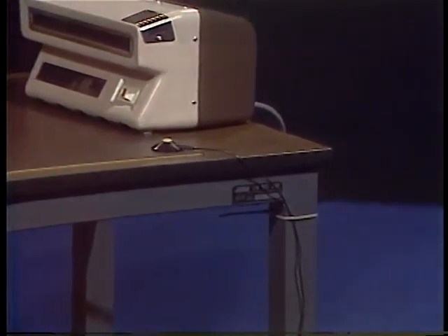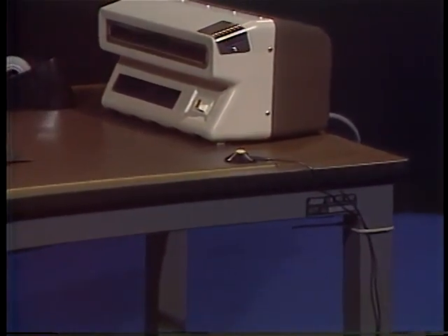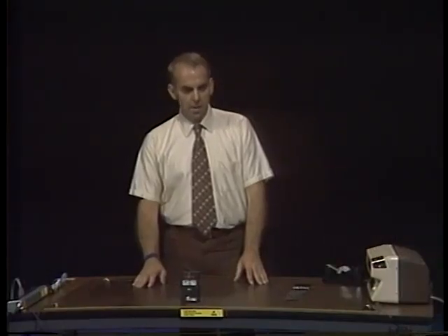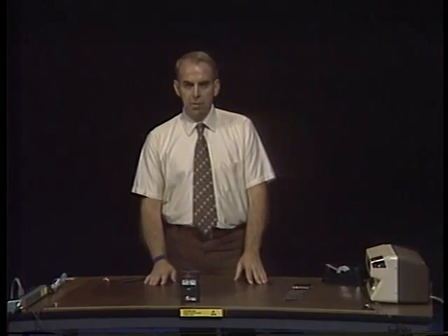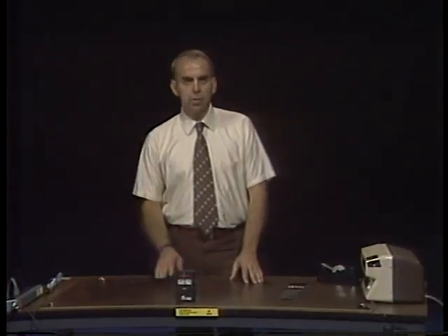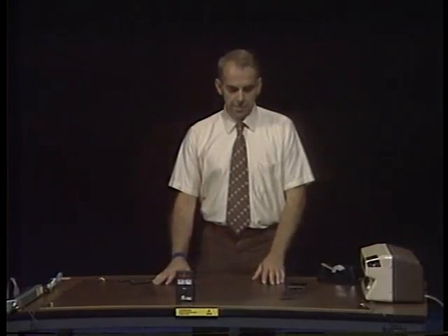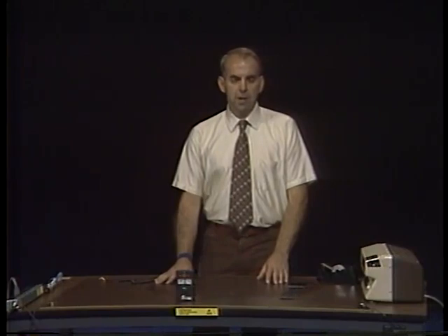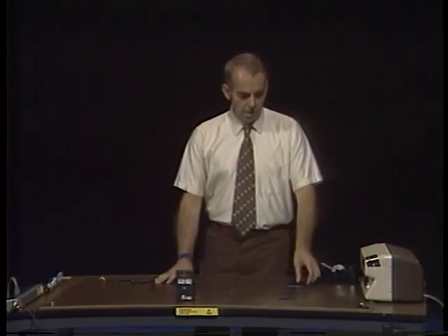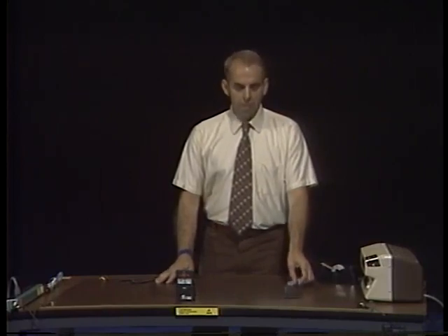Now the floor, the table, and I are all at the same potential. In the event that a table mat is not used, the floor mat may be grounded directly, but be sure to use the current limiting resistor. One problem occurs with floor mats, and that is that we don't know the conductivity of the shoe soles. To alleviate this problem, we have shoe grounding straps.